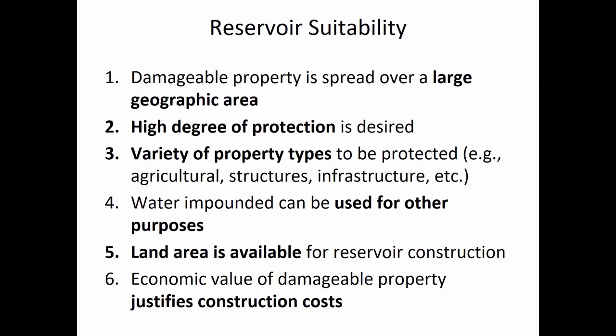And usually reservoirs are suitable when you have the damageable property spread out over a wide area. And most of these flood control measures go in one of two directions. Either you're trying to keep all of the high value things enclosed by an area that's not going to be flooded, so that is keep the water out of a certain area, or the reverse of that is you're trying to get the water to go into a concentrated zone, and that's what a reservoir does. The place that you're trying to protect is spread out over a wide area, and so you're trying to concentrate the water into a different spot. And so that makes a reservoir suitable for when the property that you're protecting is distributed.